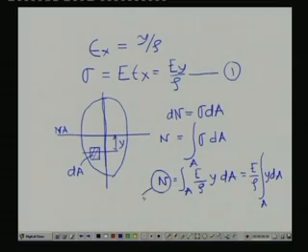It is precisely equal to 0, because there is no normal force acting onto the cross section; it is pure bending. So, if the normal force is 0, then since E and rho cannot be equal to 0, the integral of y dA over the area A must be equal to 0.